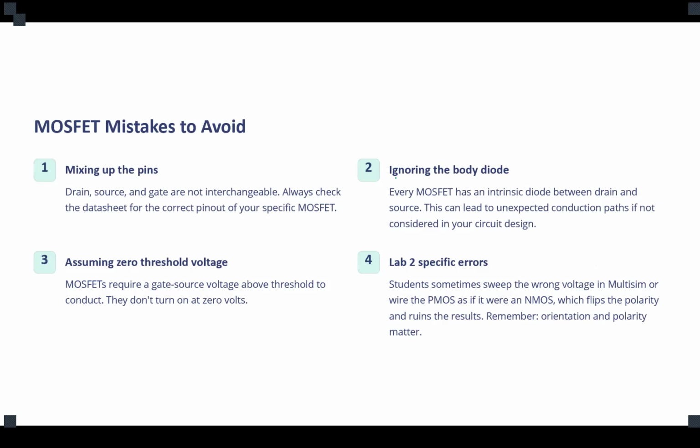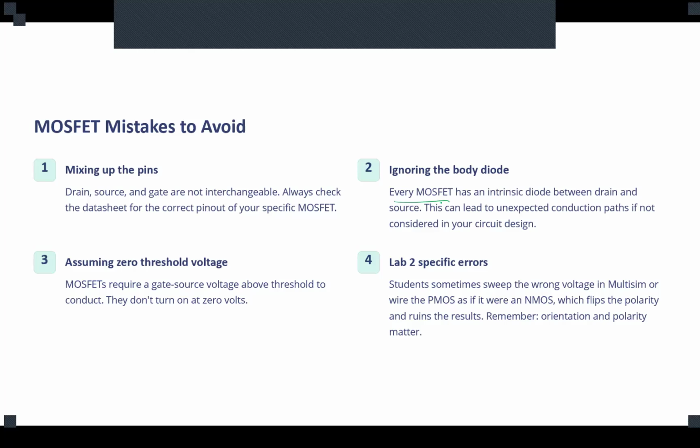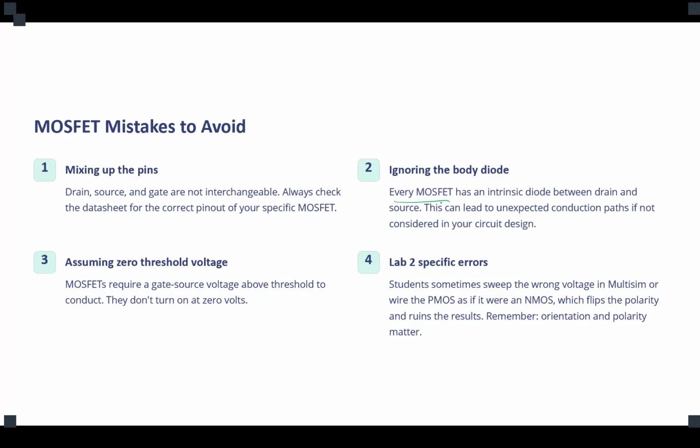Now, every MOSFET, please pay attention, has a bypass diode. So in the event of turn off, when it wants to turn off, there is a path to drive the current, so you won't force a reverse current to your switch. Does that make sense? Is that clear?